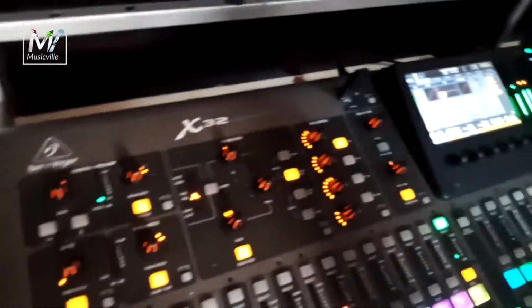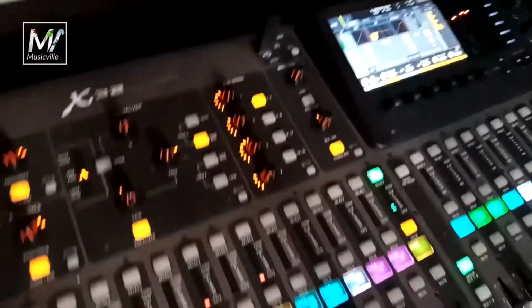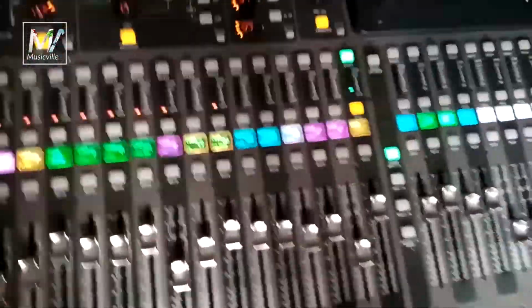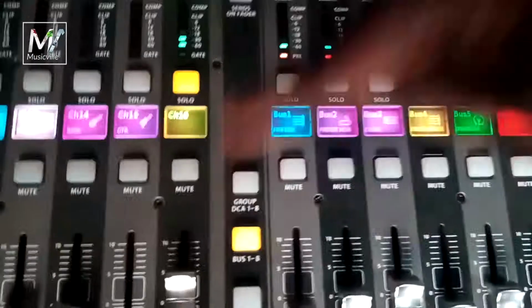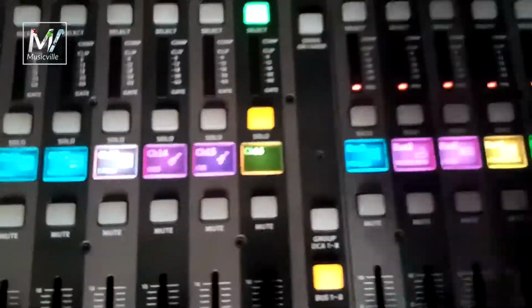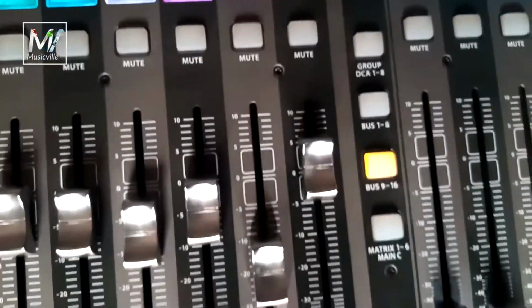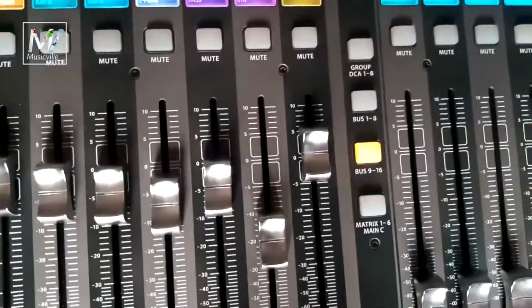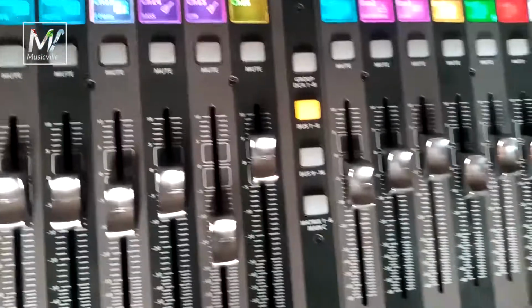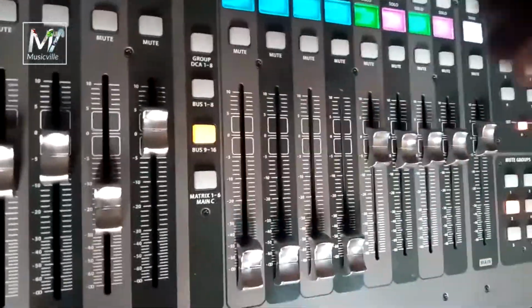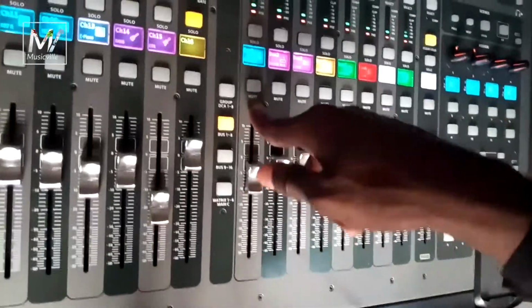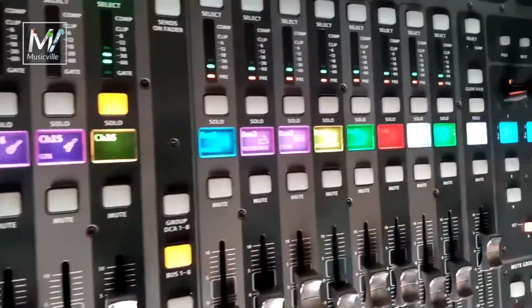your signal now goes into the mains and the buses. Come closer. These are the buses, of course. In the X32 we have 16 outputs, which includes the delay, that's the FX channels as well. But on this setup I did here, I'm using only 8. We have the FOH, the sub, the monitors, and every other part.